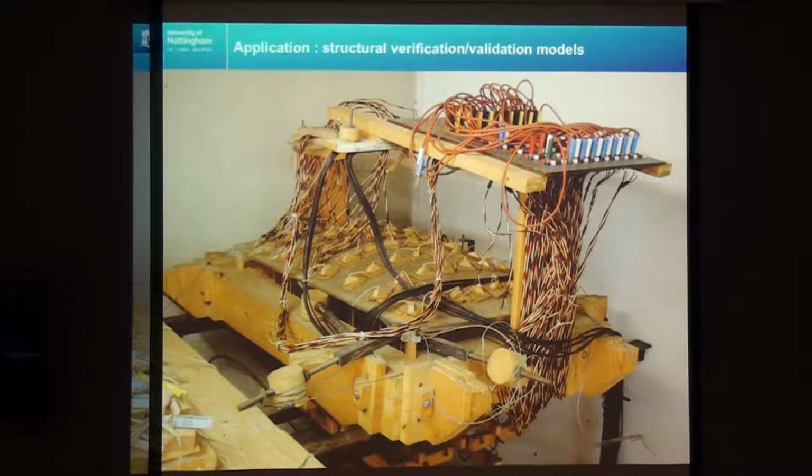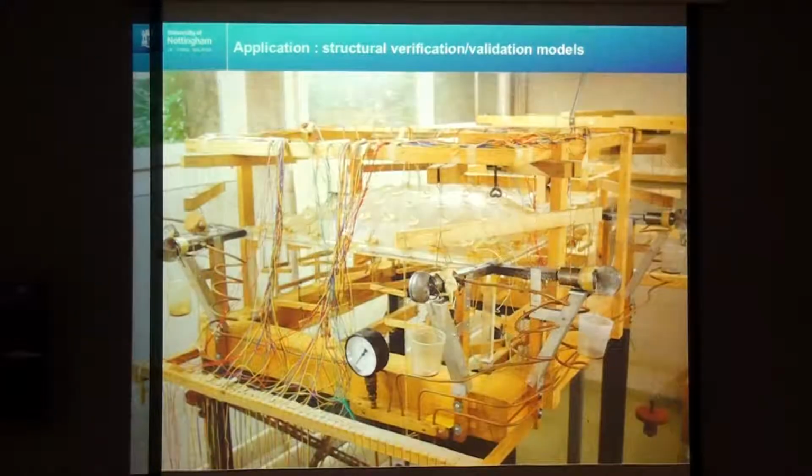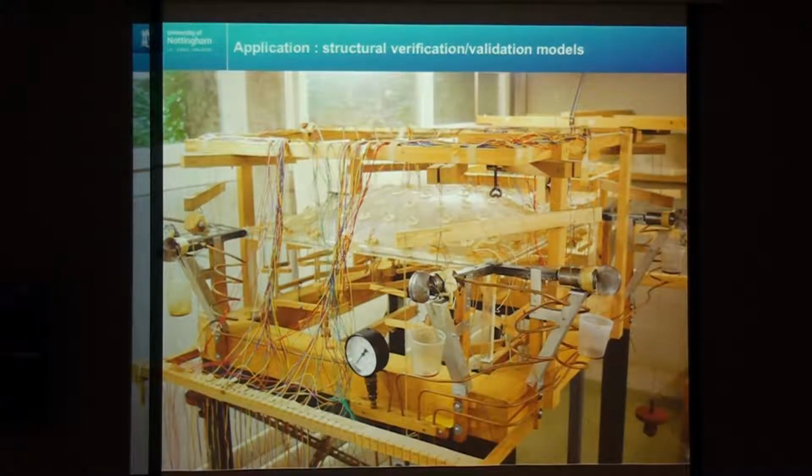For me, I think we're talking about the impact of his modelling on the design development. Actually, although people look at his form-finding methods and think of the innovative form-finding methods, I think the most important models he made were the structural verification models. Because any form that he was coming up with, using his methods, could potentially be a shell structure. But what is the most efficient, and what are the stresses within that surface? So he used the structural verification models to refine the final designs.